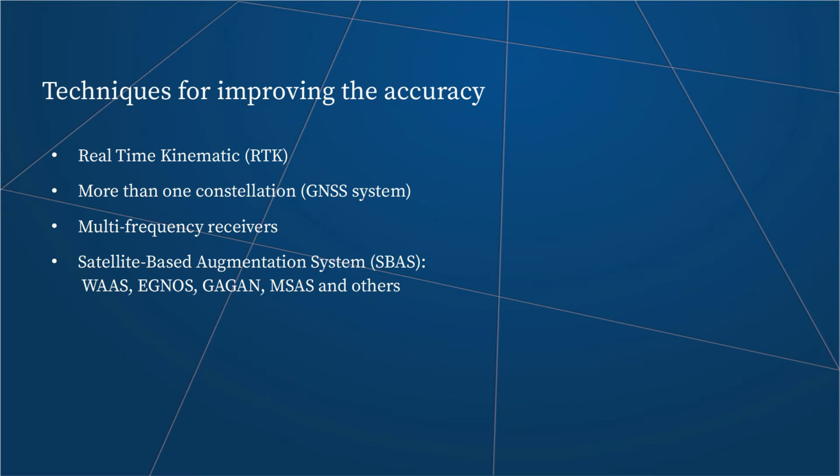Unfortunately, these systems don't improve the accuracy very much, but anyway, it's an improvement. Another way to achieve better accuracy is with the precise point positioning method. This method was initially developed as a post-processing method. It is working like this.